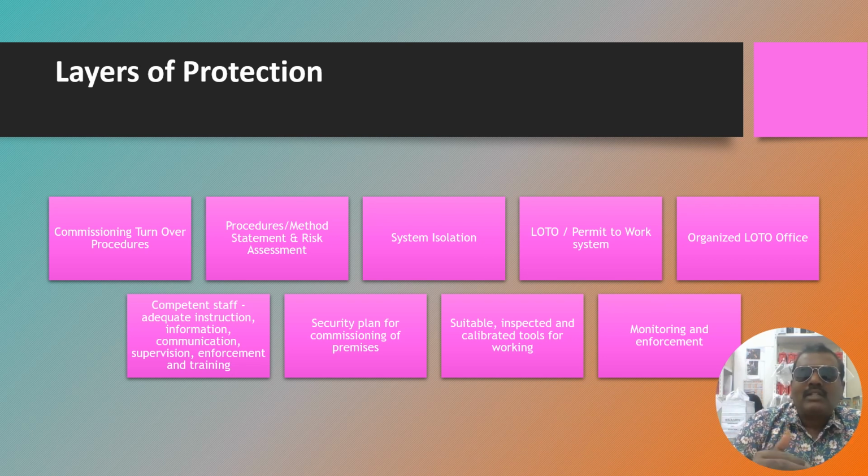Okay, now as I said, the transformer is energized, the electrical panel is energized. From there are 10 outgoings. Example, think that the last point is maybe the lighting. How does the lighting work? 13.8 steps down to 480. From the 480, they use another transformer. From that transformer, it goes as 220 or 240.